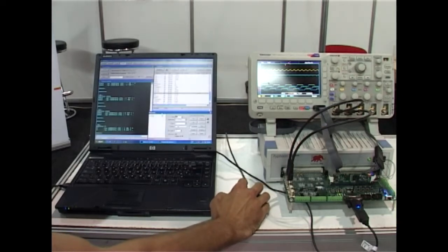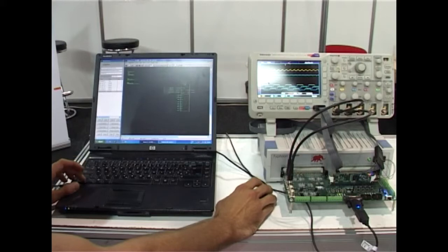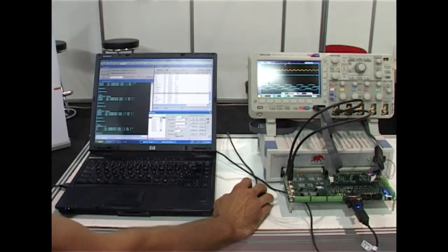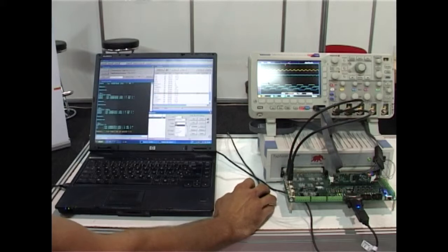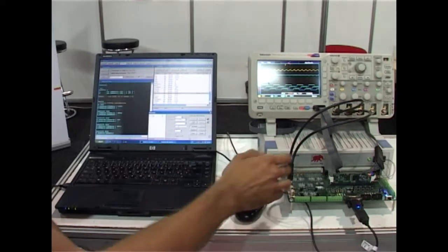For that task we have a recorder application. The recorder is a block that is housed in an application, and this is its symbol. We can add all the symbols and signals that are defined in an application to record their values. Also we can choose which signal will trigger the recorder. When we set up our recorder, we can also change the position of the post trigger. When we set it up, we send the configuration to the microcontroller.